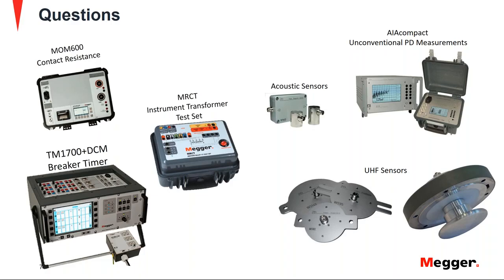place. And the beauty of the acoustic measurements is you can completely decouple these through the metallic surface of the GIS. So there are special sensors that are used to strap to the metallic surface of the GIS, which even gives you more freedom of placing your sensors along your GIS system, as you're not limited to the windows or the flanges when you're using the acoustic. Again, you can decouple these across the metallic surface, which is why they're particularly good at location.